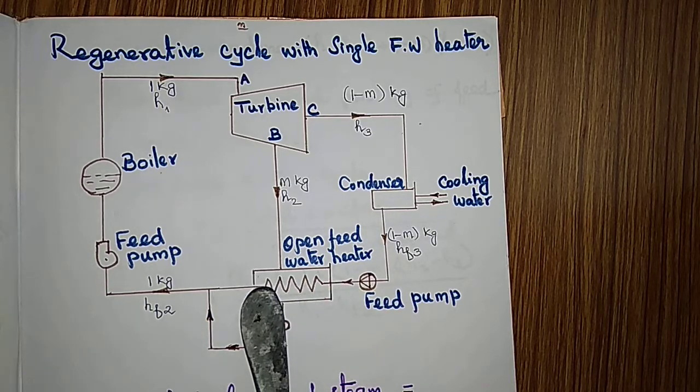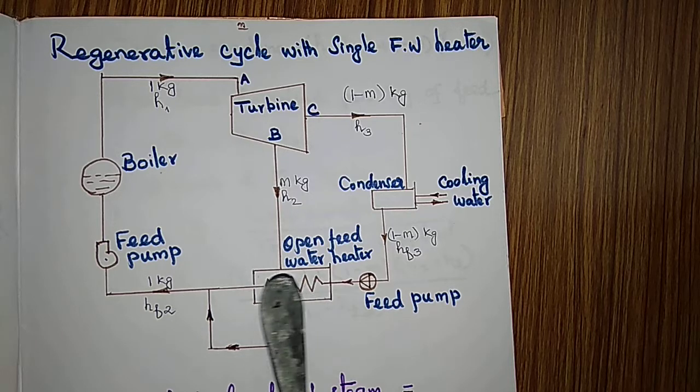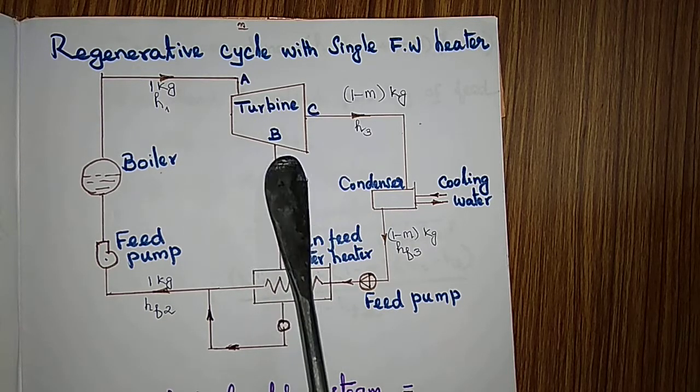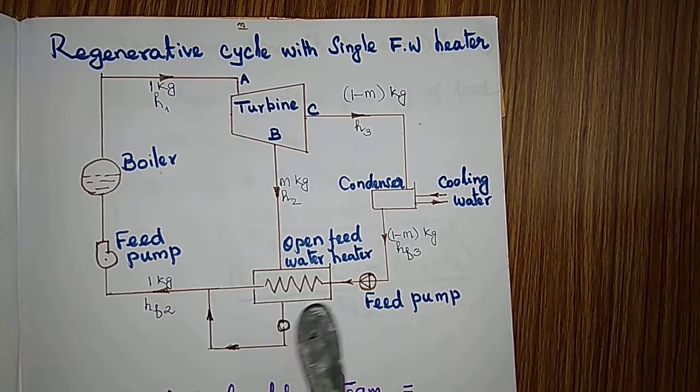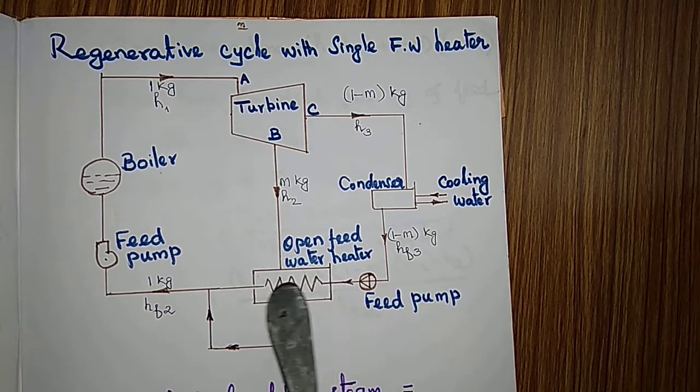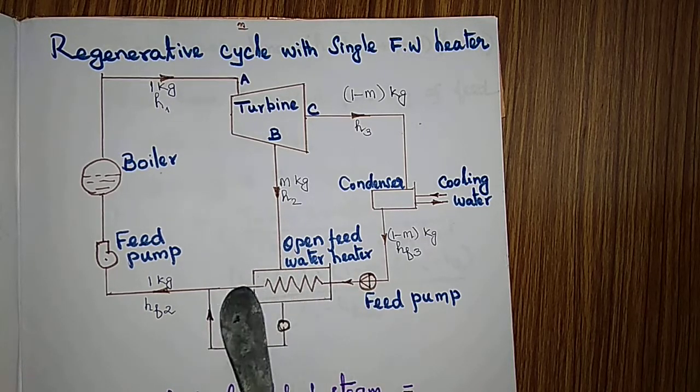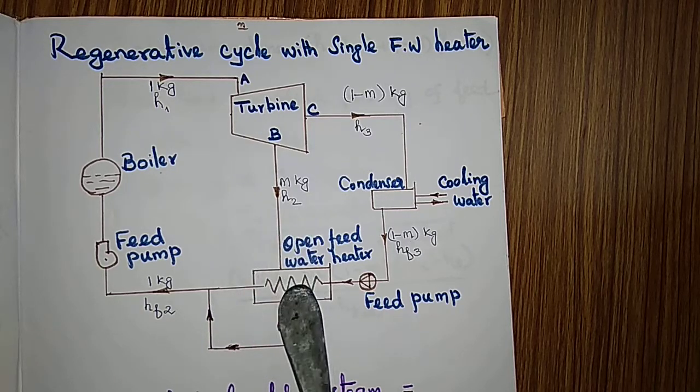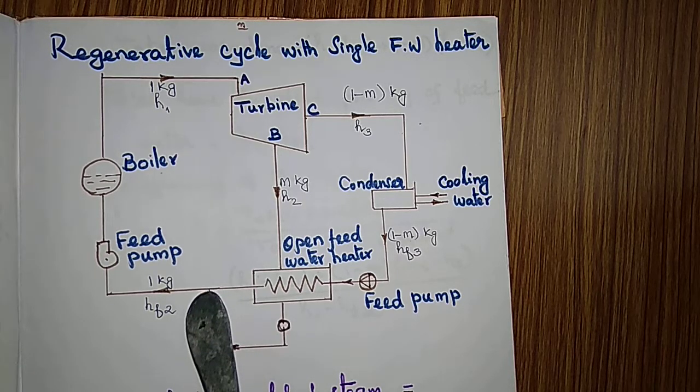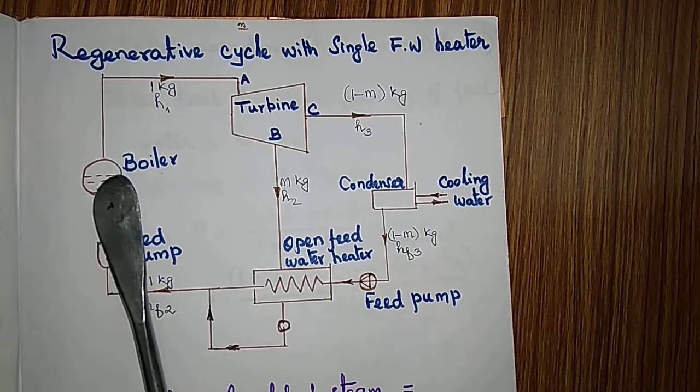That is now heated here. The feed water is heated using the bled steam. So this heated feed water as well as the steam, after giving its heat to the feed water, that is condensed, both are mixed together, and that is drawn by the feed pump and supplied to the